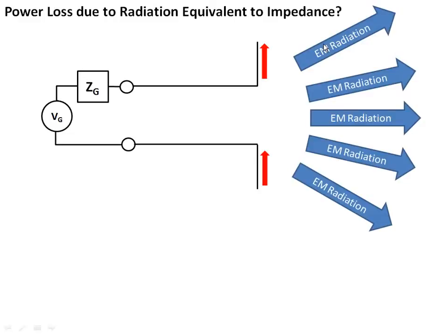And we know that when we bend this transmission line, if we can make the case that some current flows here, even though the current at this point has to be 0 and the current at this point has to be 0, if we get some sinusoidal or oscillating current, some of the energy that's used to drive those electrons, that charge that goes up and down, is going to be radiated as electromagnetic radiation, which I've tried to illustrate as these lines of radiation leaving, the blue arrows.